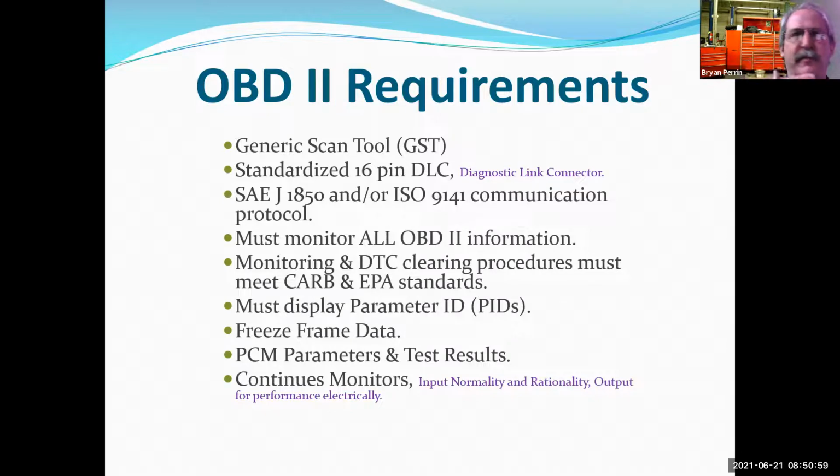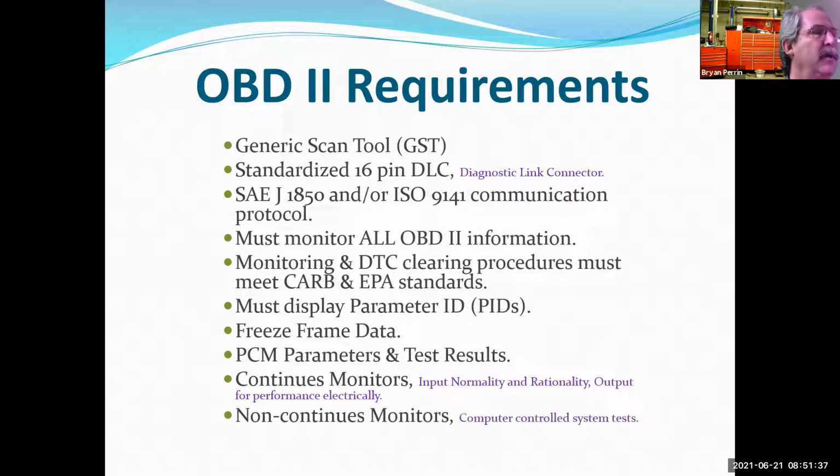So it's a simple way of saying, are the solenoids still hooked up? So again, we're not testing if the solenoid works. We're not testing if it performs what it's supposed to do or anything else. All we're saying is, hey, do I have voltage potential here because I have power going through the windings of the solenoids coming up to the end of an open circuit so I can see that voltage potential. And that's what they're doing inside the computer. And that way they know if something's unplugged. Did we do that in 96? No. Did we do that in 2022, 2021? Yes. So things have evolved.